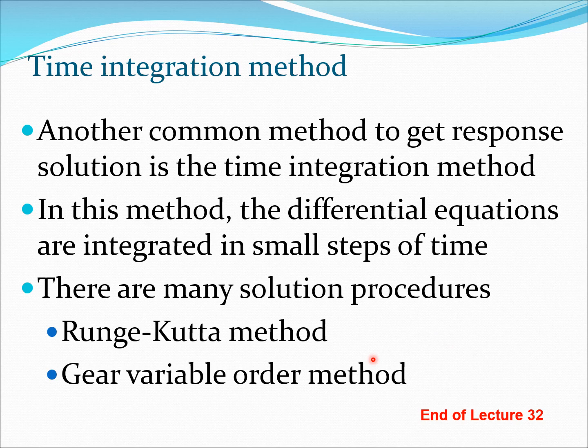You can find a lot about this by searching in Google itself. Then there is the Gear method, which is sometimes used because in rotor dynamics, sometimes you land up with stiff differential equations, and the Gear method may be good for that. So again, depending on what method you have, you can try them out, you can experiment with them, especially if you're looking at both the transient and the steady state solution to the problem.